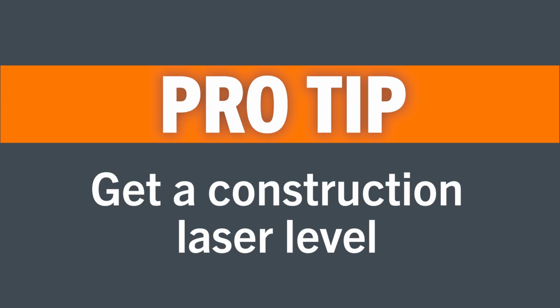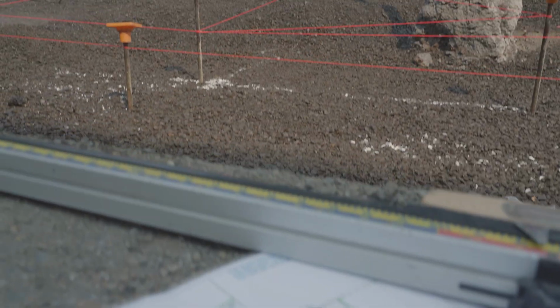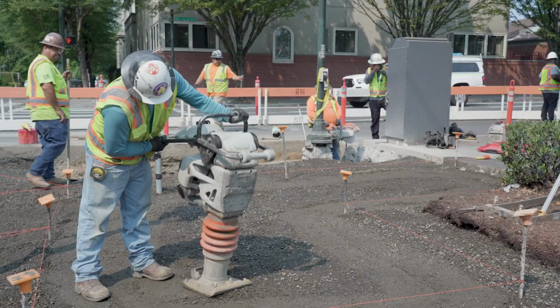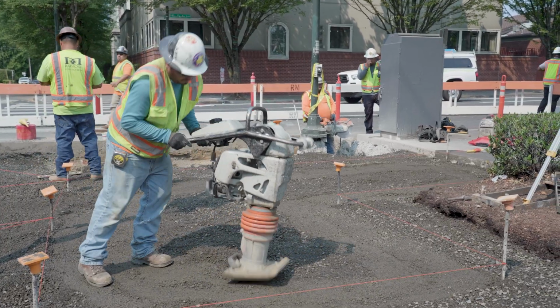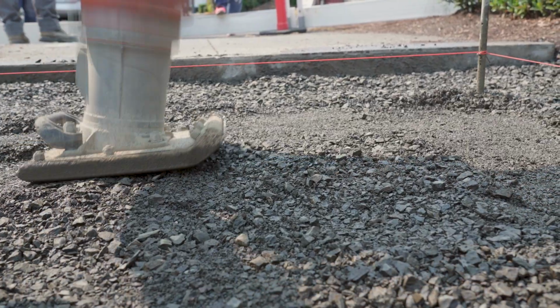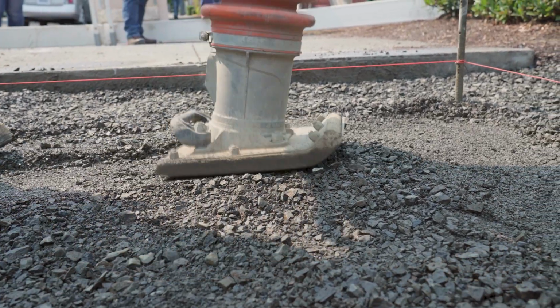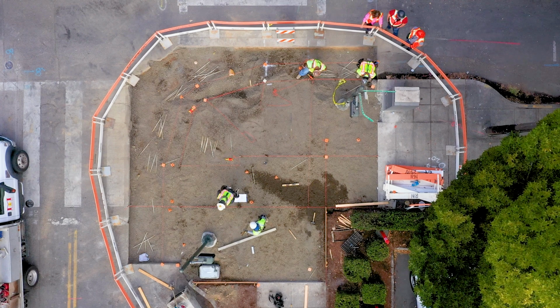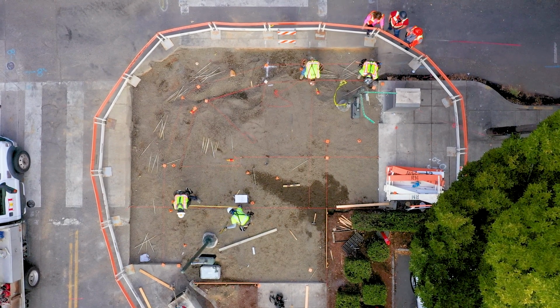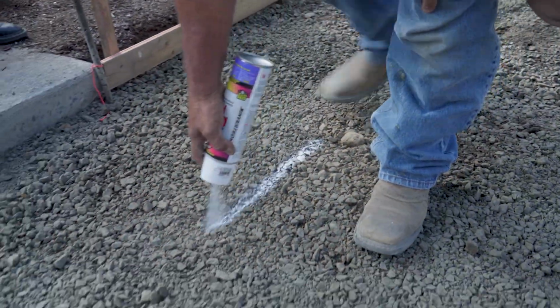Get one. As you're finalizing your levels, you'll want to begin compacting aggregate. The smartest strategy is to compact 2 to 4 inches at a time. Make sure not to overfill. So now we've got string lines in place confirming heights and measurements to ensure straight form lines. It's also a good idea to spray form lines for visual confirmation.